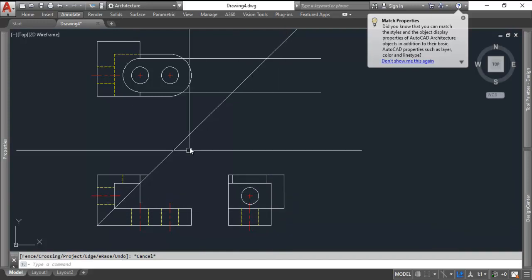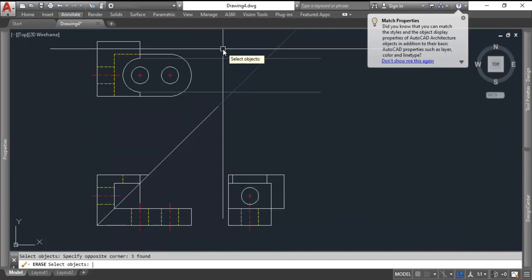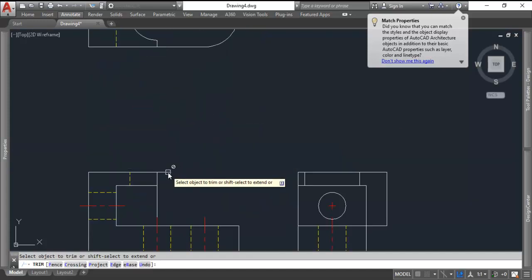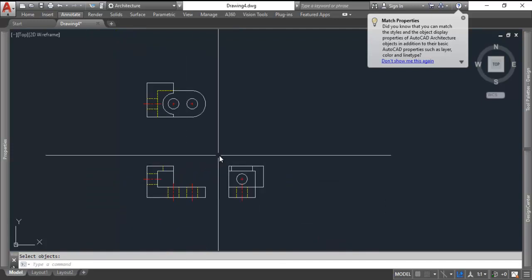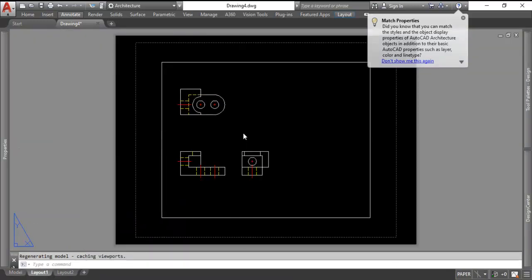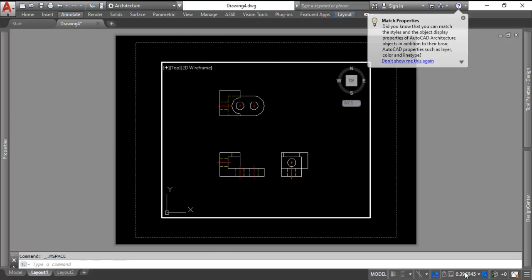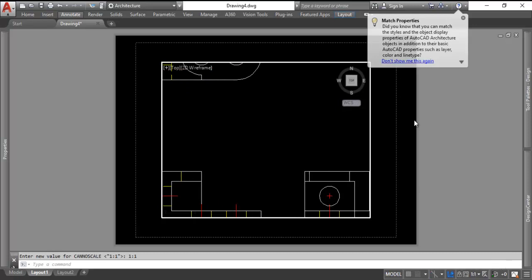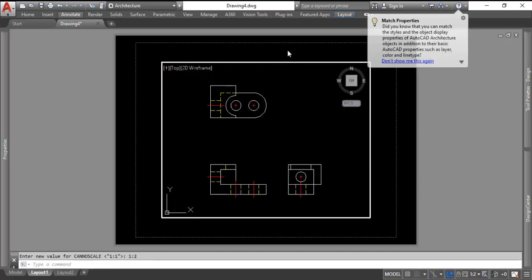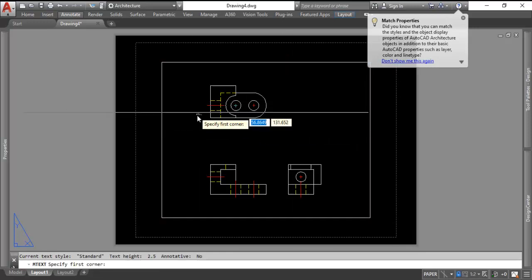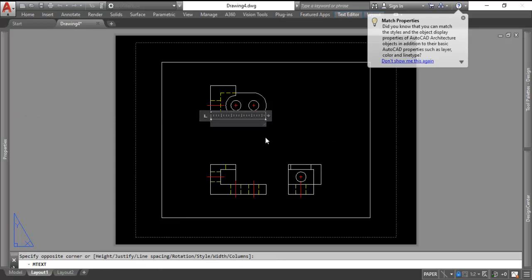There's no other hidden lines to add, so I'm going to erase my projections and delete any other stray lines that may exist. And then I'm going to go into my layout, set our scale. Most of these are fitting on 1:1. This is not, so we'll have to do 1:2, which is half scale. Double click outside, lock it down, M text, Control U,